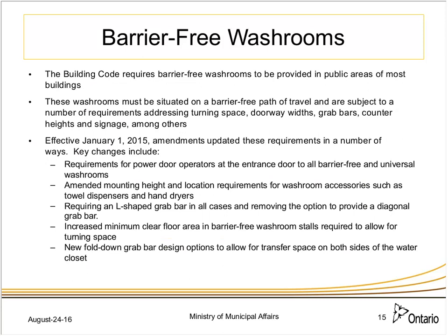Anyway, so barrier-free washrooms, we made some changes. They're largely, with the exception of the power door operators at the entrance door to a washroom that has an accessible stall. So that's not the stall itself, that's the door by which you gain access to the washroom area. It has to have a power door operator, or none at all, where you have no door, so it's just free access.